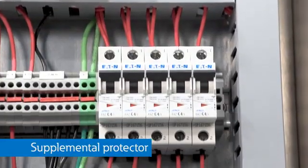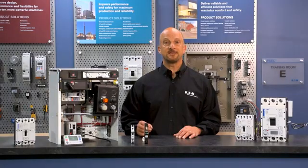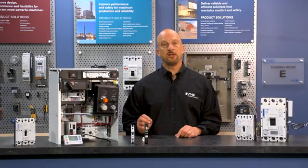Supplemental protectors are often used as a circuit breaker inside industrial control equipment. Most people believe that these are standard breakers, but they're not. The UL 1077 standard defines a supplementary protector as a manually resettable device designed to open the circuit automatically like a breaker, but with limited short circuit protection. They provide protection for only one device, and they're always located after the branch circuit protection.